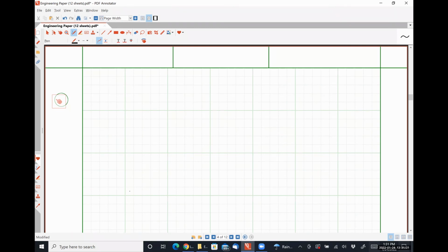Okay? But having some means by which to determine your large signal operating point with channel length modulation included can be useful, because for small channel devices, it can be a very large difference in what you think the operating point is if you neglect channel length modulation versus what the actual operating point is.